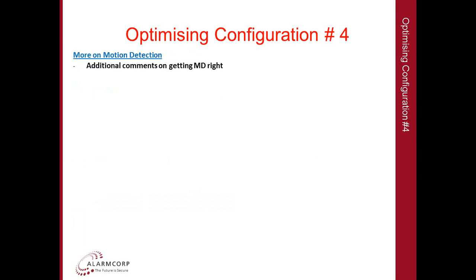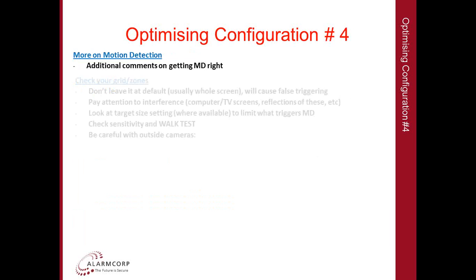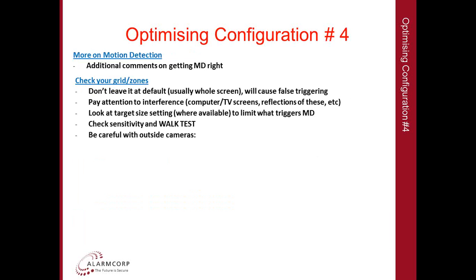Right. Now let's look a little bit more at motion detection and get some additional comments on getting it right. Check your grid or zones. Do not leave motion detection at default. Typically this is the whole screen. This will often cause false triggering.